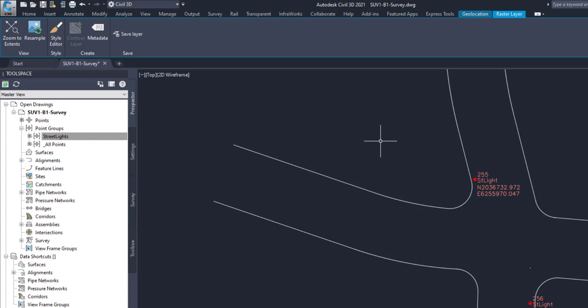With that done, I'm going to save my drawing. But before I do that, let's change our scale. So the text is annotative. As I scale in and I scale out, the text will automatically be updated. All right, I'm going to save my drawing and we'll continue on with it in activity 4C.